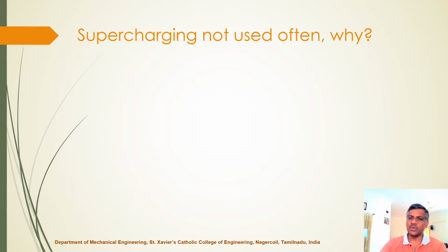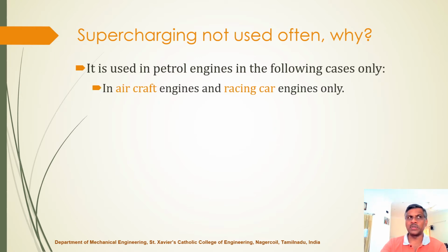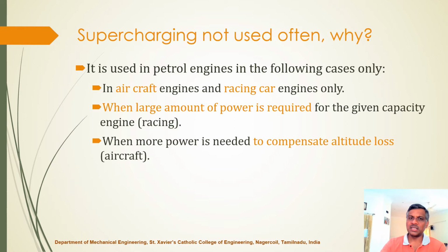And supercharging is not commonly used. Why? Because of the following reasons. Aircraft and racing vehicles only we use it. Because for supercharging, to run the compressor, we have to give mechanical energy. And that mechanical energy has to be taken from the cylinder itself. So large amount of power is required. And power is wasted. The power developed in the cylinder is used to run a compressor. So a lot of power is wasted.